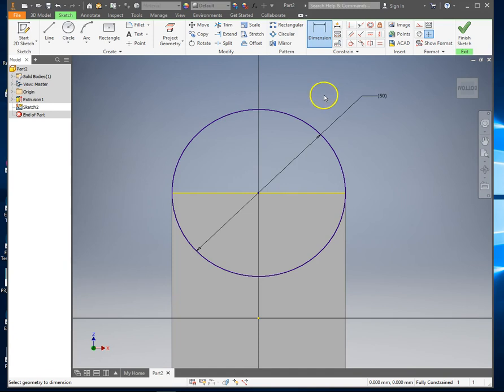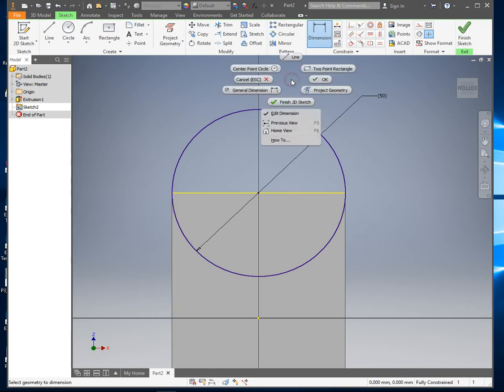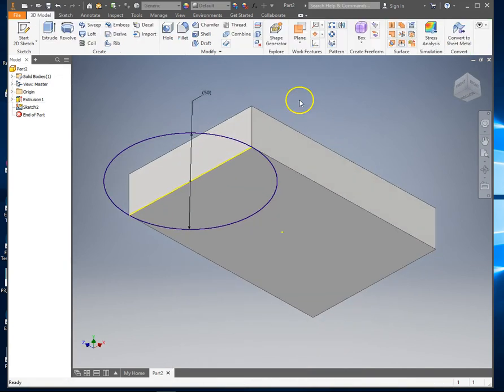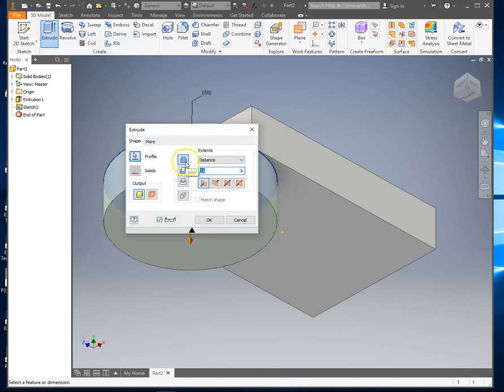Okay, so now your first 3 questions in the quiz are about Boolean operations. Boolean just has to do with mathematical logic and different functions, and there is math involved in creating solids. But the Boolean operations are all under extrude, so I'm going to show you those. Right click, finish sketch, and then I'm going to use extrude. So these are your Boolean operations: